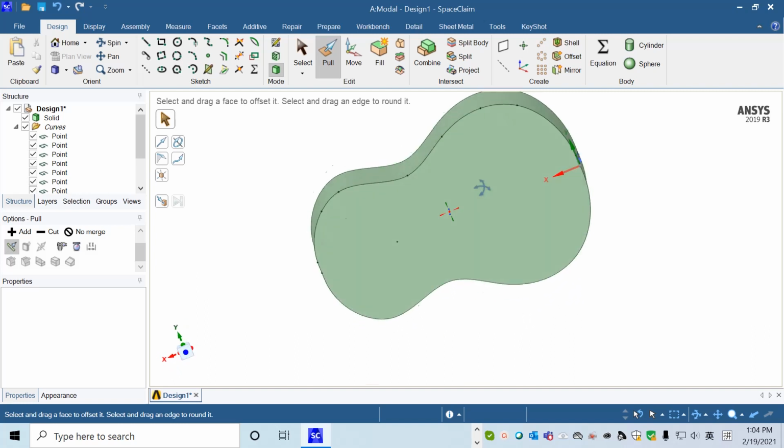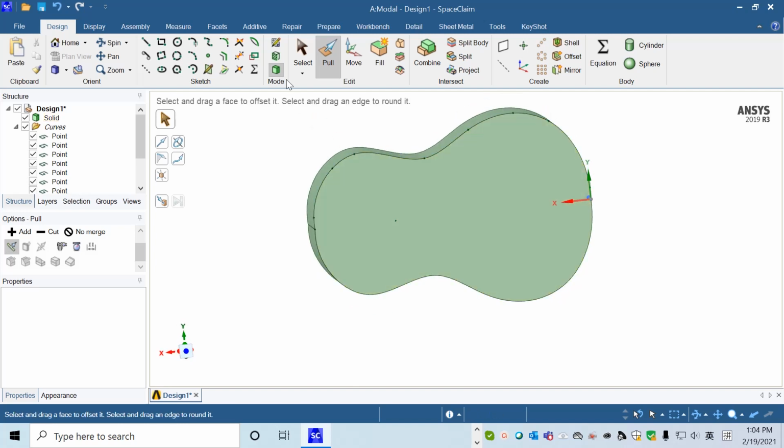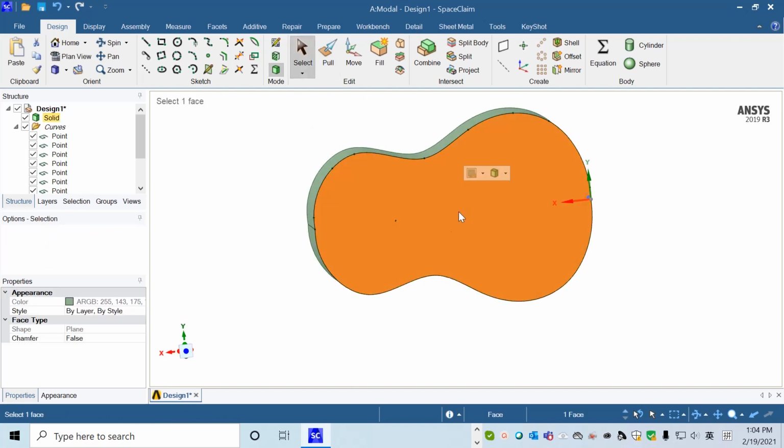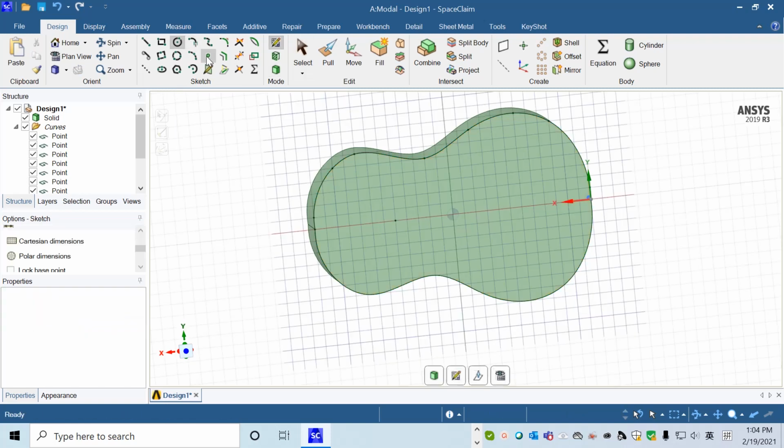The next step is we'll dig a hole into it. To do that, we first select this surface where the dot is located. So make sure that you choose this surface, and then we'll use this dot to help dig a hole here. And then I click on this circle drawing. So you'll see that the sketching surface will be created along this surface, where we'll use this dot at the center to create a hole which is 45 diameter, and then escape,